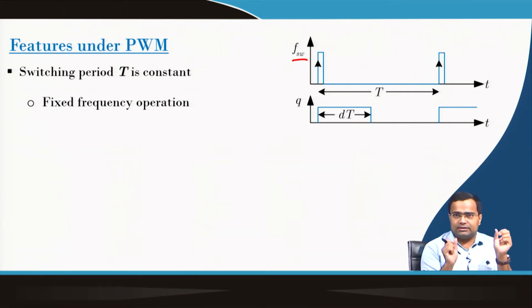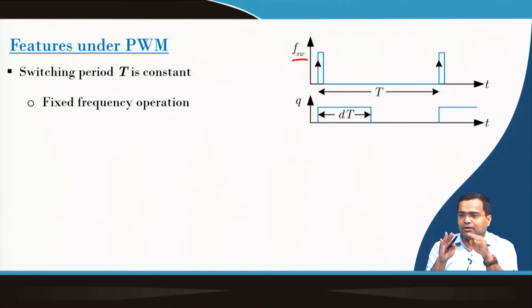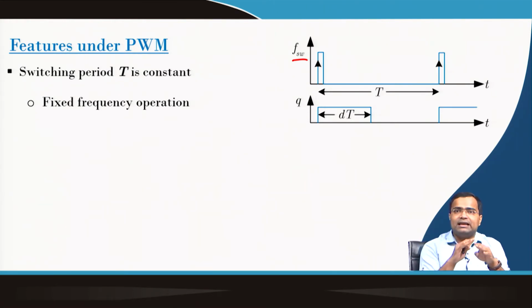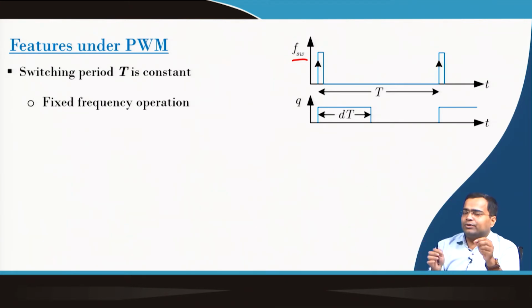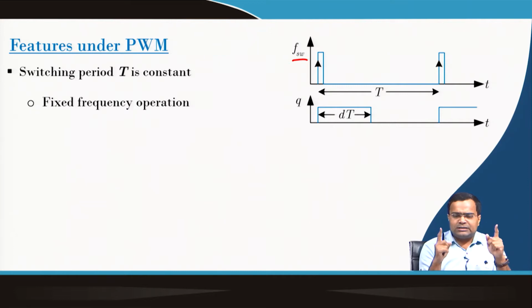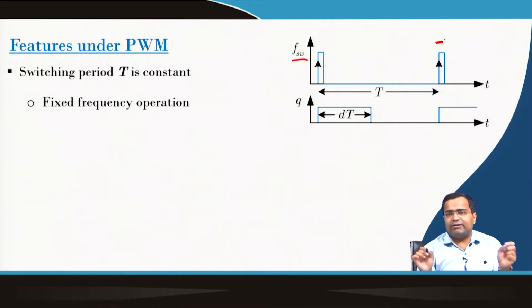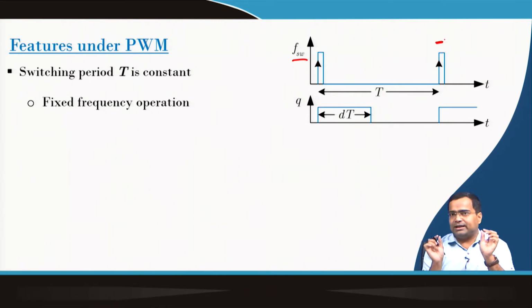This randomized technique is intentionally applied in order to spread the spectral component, because we also want to meet EMI compliance. One way to do that is to spread the spectrum by adding some variation in the switching period.